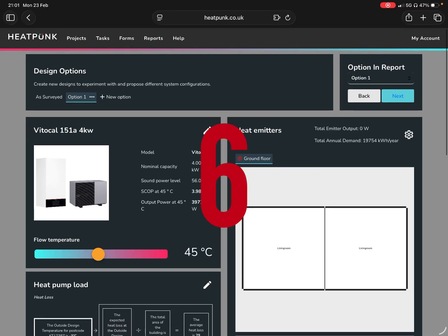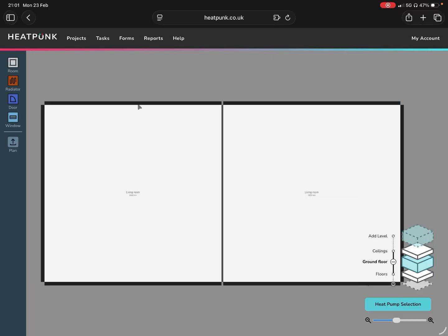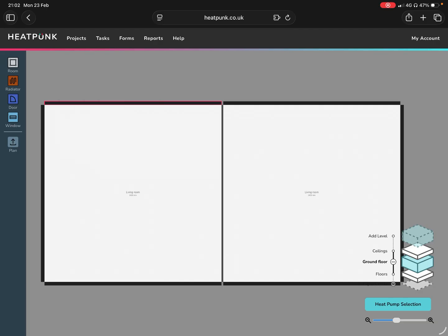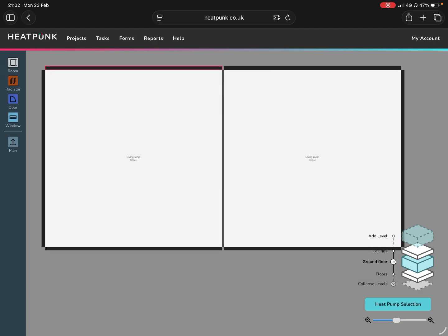Also knowing and paying attention to the correct materials. So different walls can have different materials. You can have, for a new build, these values all inputted default on both programs, but your surveyor needs to be able to tell the difference between a solid wall, a header and a stretcher brick wall, and the different surface finishes. All these things make a difference, and the more detail orientated your surveyor is, the more accurate the sizing of your heat pump and each room by room's emitters can be. Many factors, and experience and knowledge goes a long way.